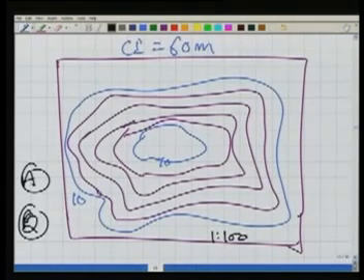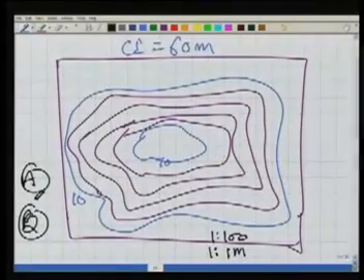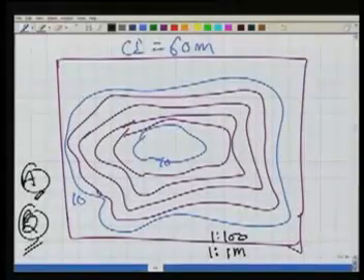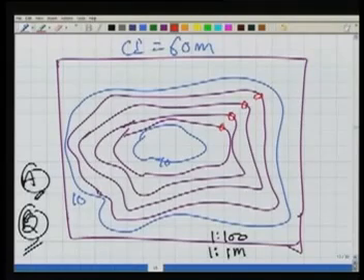The second possibility, B, this map could have been a very small scale, for example, 1:1,000,000. Now, out of these two cases, large scale and small scale, how should the contour intervals be decided? Is there any relationship between these two? If the map is large scale, we are able to plot more details. We will be able to show these individual contours separately because my map is very large.